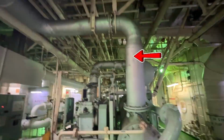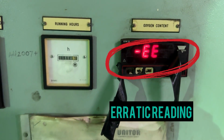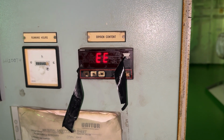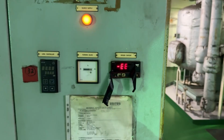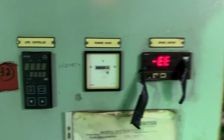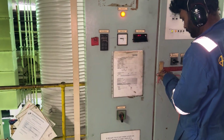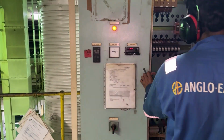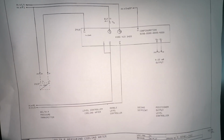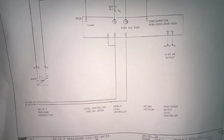to the refrigeration unit. So the gas engineer told me the oxygen content meter in the panel is sometimes showing an erratic reading and sometimes it is showing a proper reading. And also he said that the water level controller display is not showing anything. So we begin our troubleshooting to resolve this issue. So first I decided to check the water level controller. This is the circuit diagram of the water level controller.